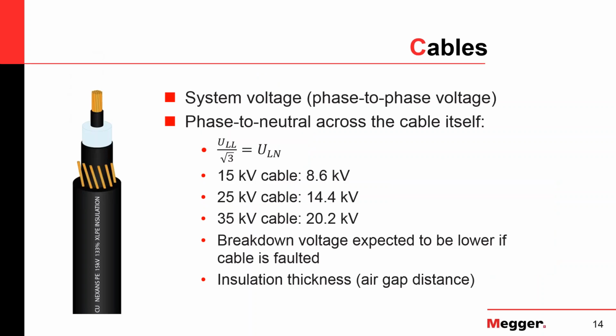Just speaking in general, so we have an understanding what we're actually talking about here. When people say, for instance, 15 kV cable, everything in the power industry is always rated three-phase. Nameplates, it's typically referring to three-phase. So that means this 15 kV is actually a system voltage. That means it is a phase-to-phase voltage.